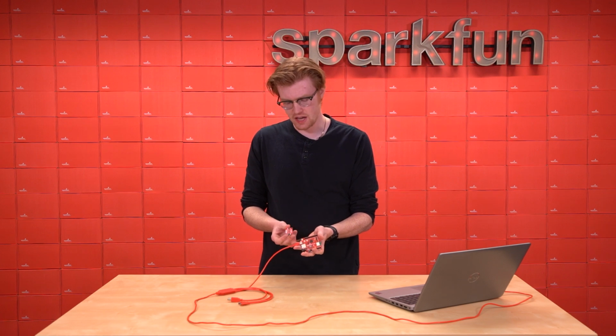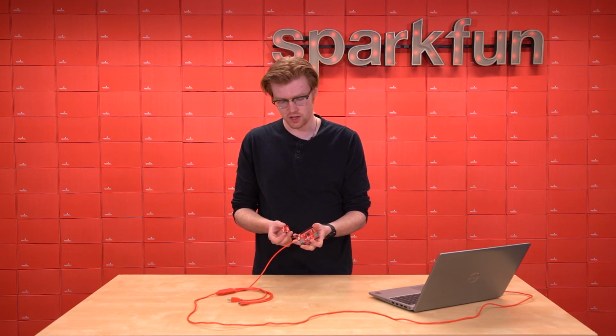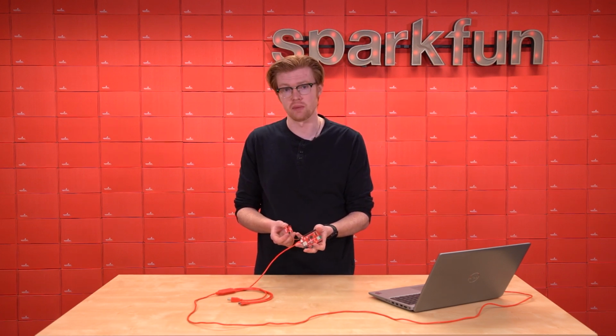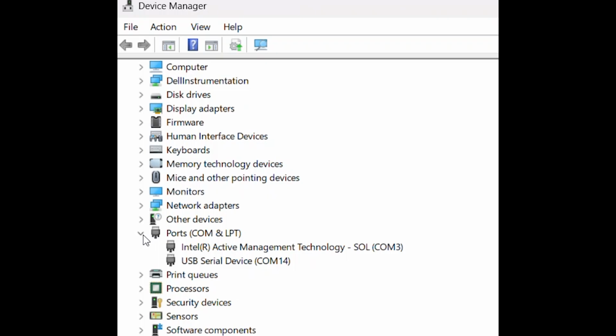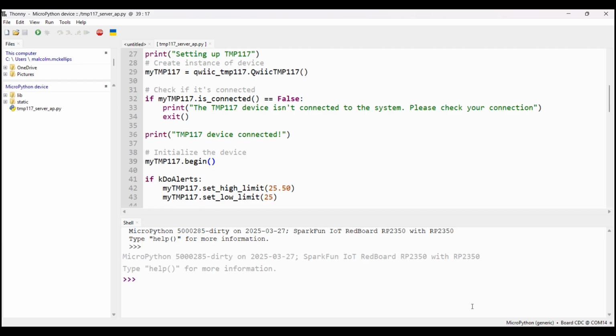Here I have the TMP117, an RP2350 IoT RedBoard flashed with MicroPython, a Qwiic connector, and a USB-C cable. When I connect the USB-C cable to my Windows computer, the board is enumerated as a COM port. And using the Thonny IDE, I can find my board, connect to it, and get access to the MicroPython read, execute, print loop. Right here, I can run individual lines of code directly on my embedded platform without having to create and compile a standalone program.